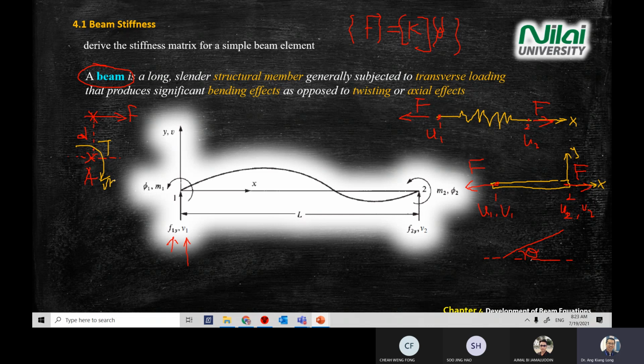Torque or moment. That's why from this point 1, you have a moment 1 here because of force number 2. And if you stand at point number 2, you're seeing F1y produce a moment also. So that's why for point 1, you're seeing moment 1, M1, and the twisting angle theta 1 or phi 1. As you can compare the 3 scenarios here, you should see the differences.